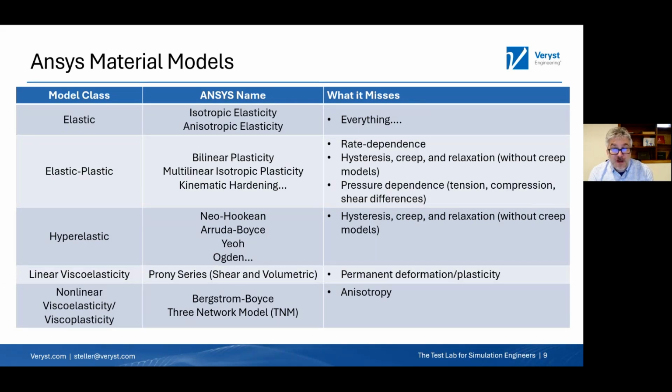That's a good question. If you're talking about long fiber composites, I'm not as familiar with material models for those. If you're talking about short fiber composites, like short glass fiber filled polycarbonate, I have to be a little careful here because I always get myself in trouble. Most built-in finite element codes just don't have anything that can get a nonlinear stress strain response with rate dependence and anisotropy. So it becomes difficult.